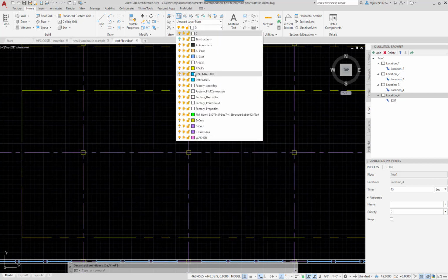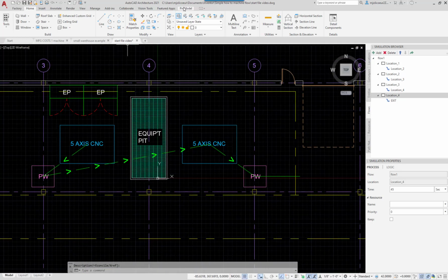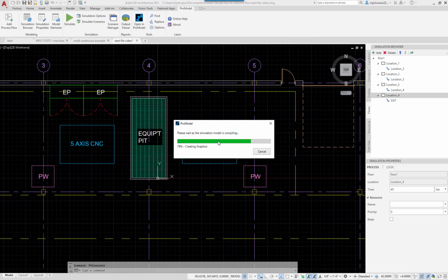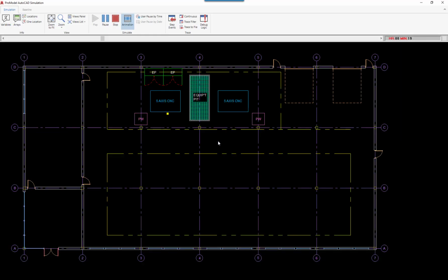We can now test the flow of the simulated system by selecting Run from the ribbon. We see the yellow squares representing the part moving from station to station, and we can control the display speed by using the slider in the ribbon. A clock in the upper right tells us where we are in the 40-hour simulation run.